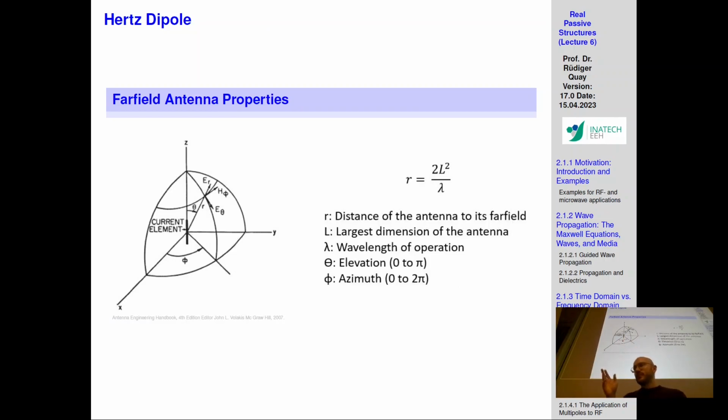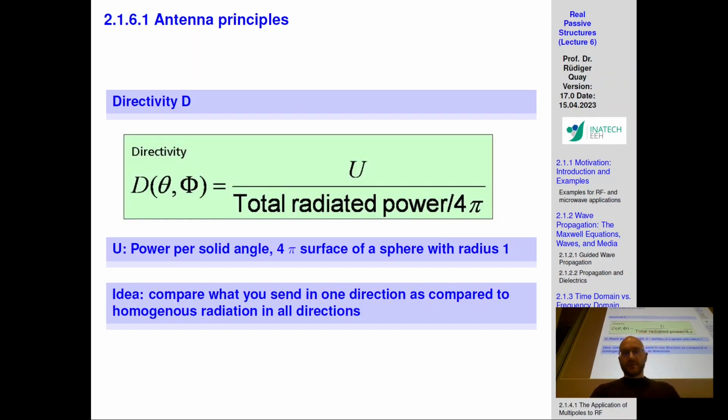Important things to remember from the antennas were the antenna parameters, and how an antenna plot looks for a far-field plot. Antenna parameters such as the directivity. An antenna doesn't just radiate out in all forms and shapes, it radiates in a certain direction. What you want your antenna to do is not radiate chaotically anywhere, but to radiate at a certain point and try to focus the radiated energy there. This ability to focus that energy is called the directivity of the antenna, taken with respect to an isotropic radiator, a radiator which radiates in all directions equally.